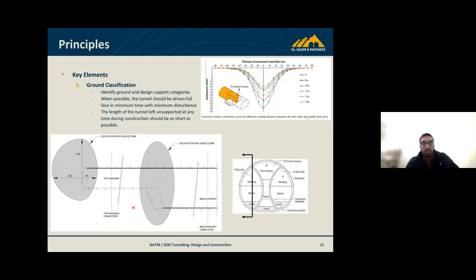The curve that we get out of that is quite key when you're designing these tunnels, and that can be done using an empirical method, not any fancy finite element model or anything like that. A simple Excel sheet or hand calcs can give you quite a good curve as to how the ground is essentially going to react.